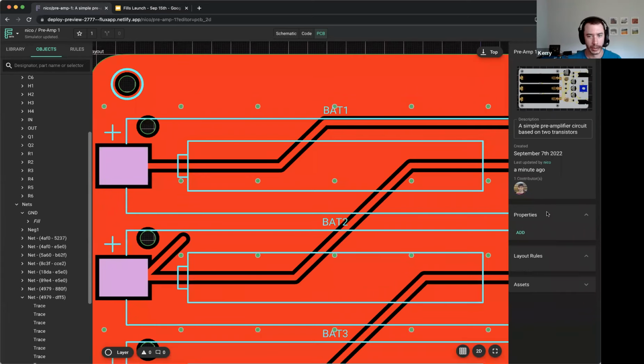I also think that one of the dream features for this type of application is auto stitch vias. Why should I even have to define the proper spacing between the vias? It should just know, based on the ground density and the current density and whatever, where an appropriate place to add vias is. And it should stitch all my islands for me. I shouldn't have to worry about the spacing at all.